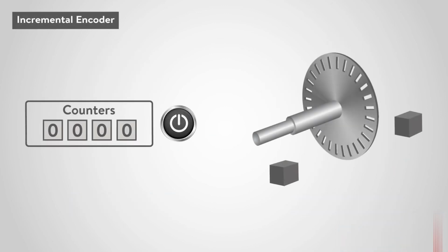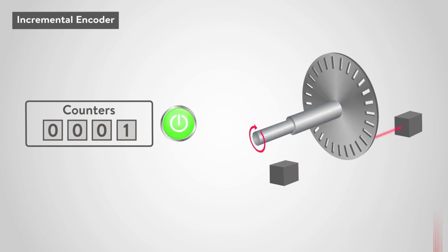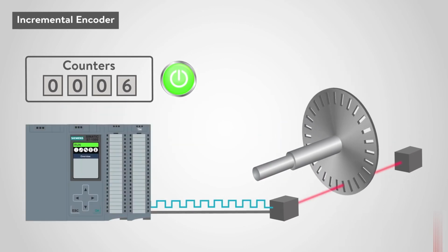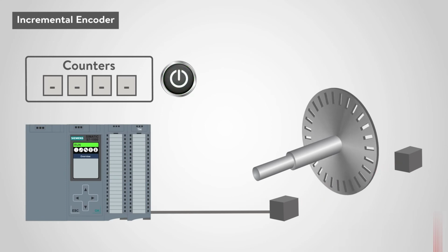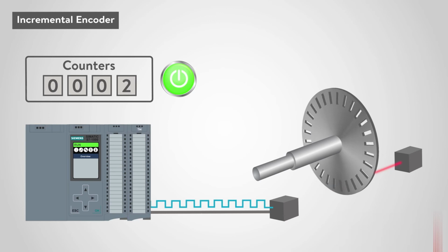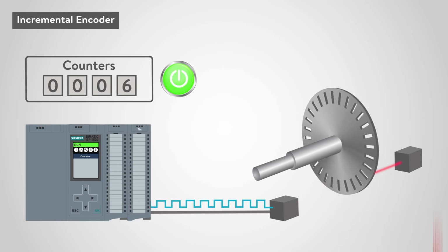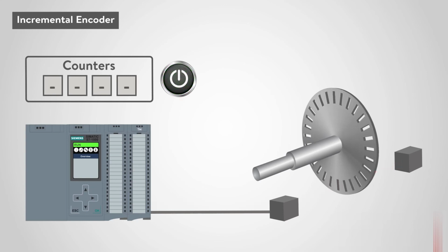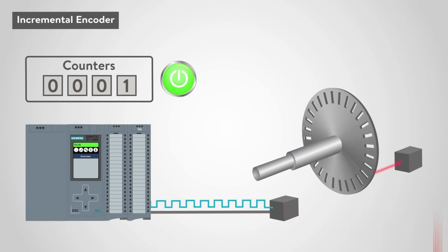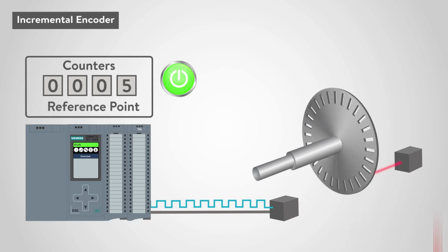For incremental measurement encoders, the output signal is created each time that the shaft rotates a measured amount. That output signal is then interpreted based on the number of signals per revolution. The incremental encoder begins its count at 0 when powered on. Unlike the absolute encoder, there are no safeguards regarding the position. Because the incremental encoder begins its count at 0 on startup or power disruption, it is necessary to determine a reference point for all tasks requiring positioning.